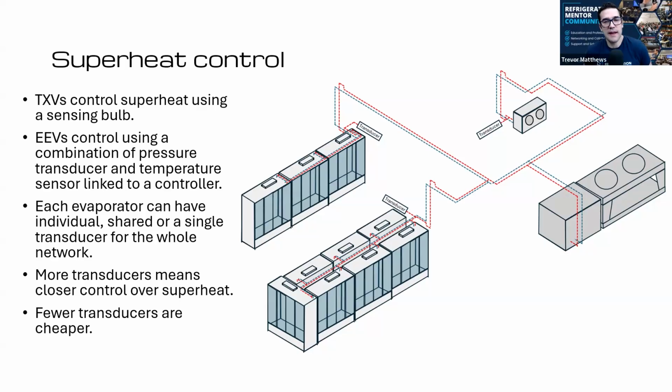Yeah. And I think that is the big thing right there. So thanks for pointing that out, John. Inside all these controllers, there are going to be different parameters. And honestly, most technicians probably don't know that there's a probe error parameter that'll say, okay, it goes to 50% valve and the valve stays at 50%. So that 50% could either flood back to the rack, or it could overheat. Either or, you don't know, because it's like overriding into a manual position where it's not going to modulate the valve. Is that correct, John?